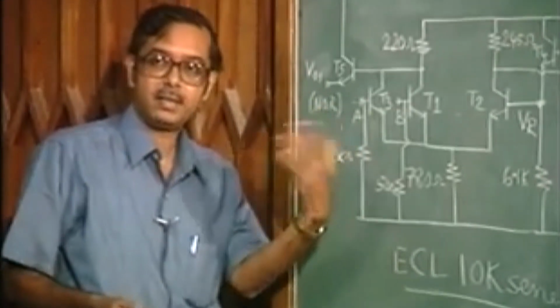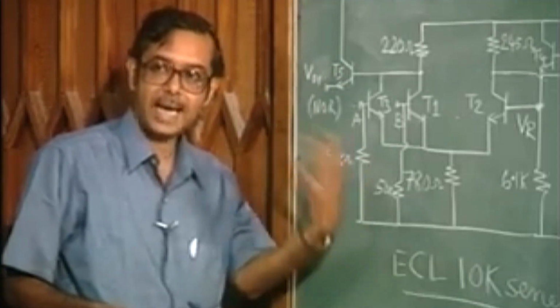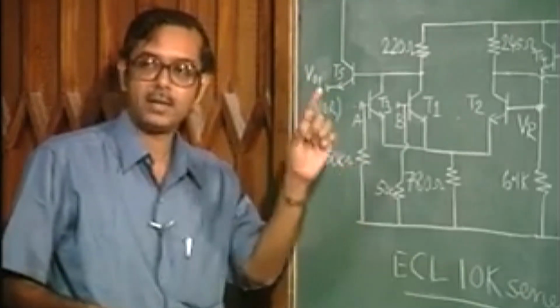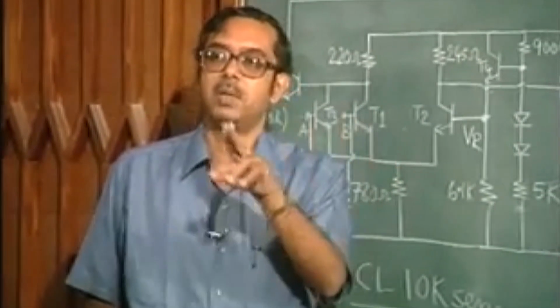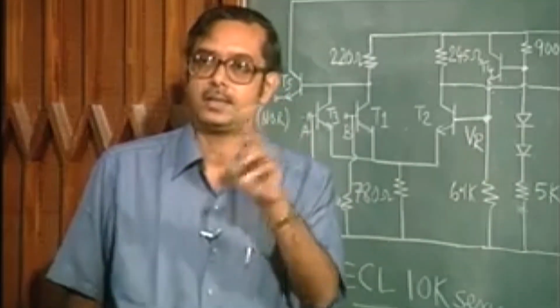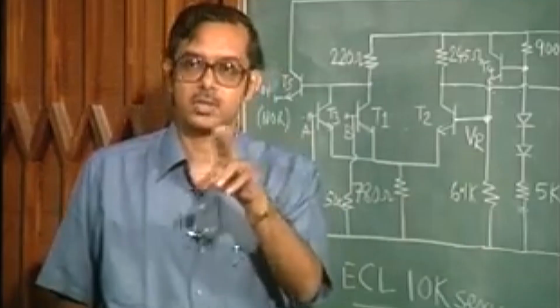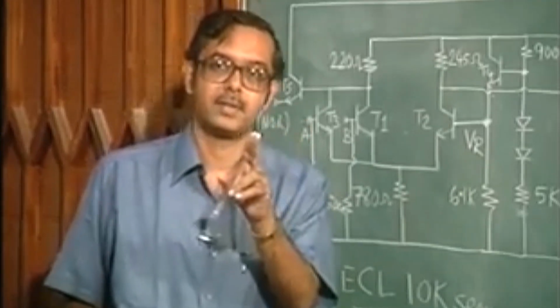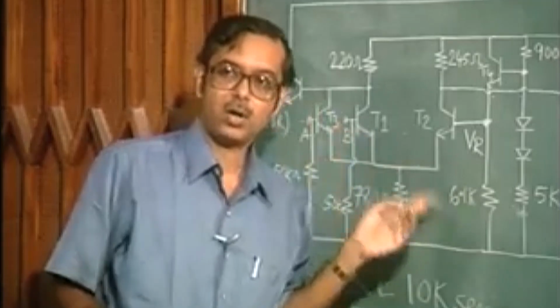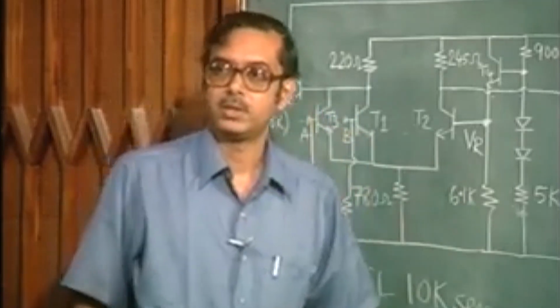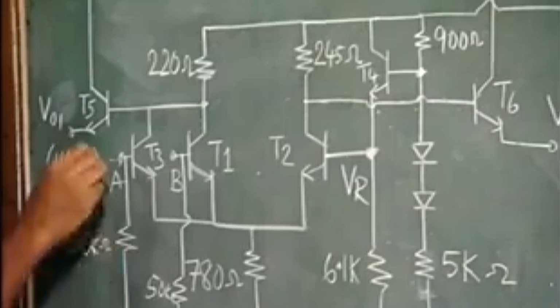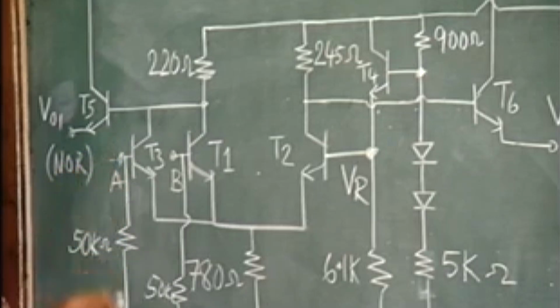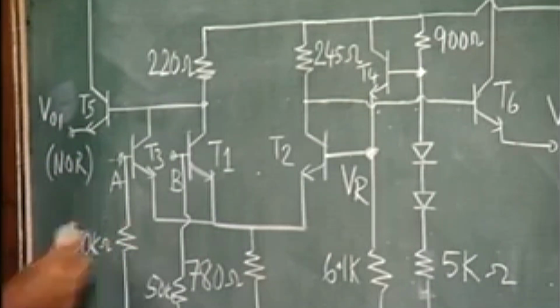Whereas in a NAND or AND configuration, if any input is 1, the output does not depend on that input, but on the other inputs. Any 0 is going to force the output to 1 in a NAND, whereas in a NOR any 1 is going to force the output to 0. Anyway, that is why you have a resistance at the input, which means that any unused input has a logic 0.